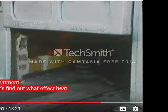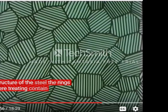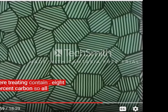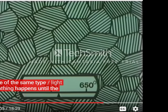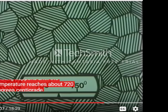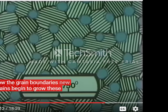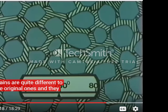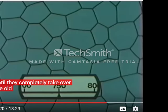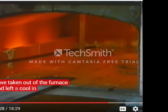Let's find out what effect heat treatment has on the grain structure of the steel. The rings we're treating contain 0.8% carbon, so all the grains are of the same type, pearlite. Nothing happens until the temperature reaches about 720 degrees centigrade. Now at the grain boundaries, new grains begin to grow. These new grains are quite different to the original ones, and they grow until they completely take over the old structure. Here we're normalizing, so the components are taken out of the furnace and left to cool in air.